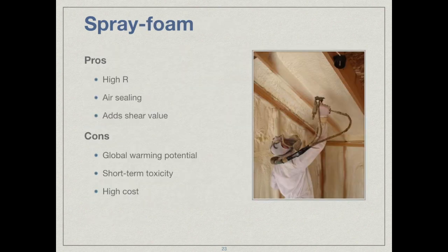A lot of people are interested in spray foam as a quick fix to make the home both airtight and very well insulated. The closed cell spray foam products have a high R value. They're great for air sealing, but they do have some drawbacks. One of them is that they're very expensive, and the other is that they have a high global warming potential.